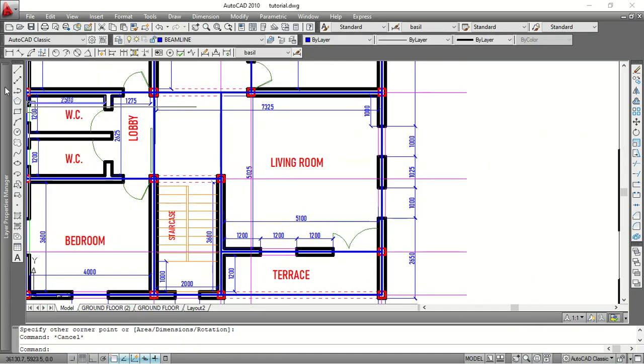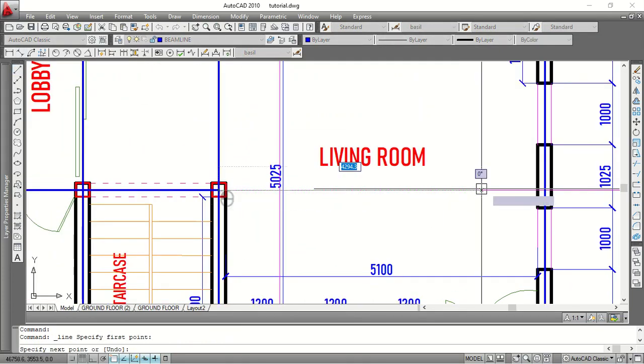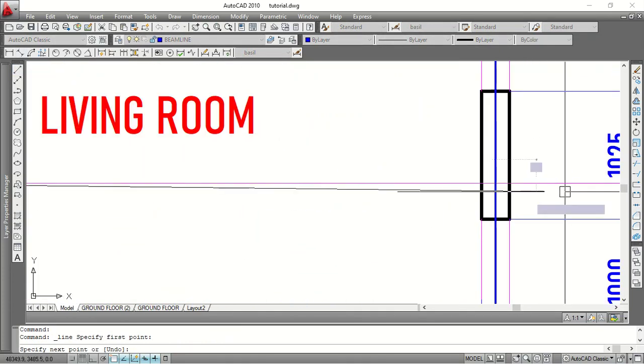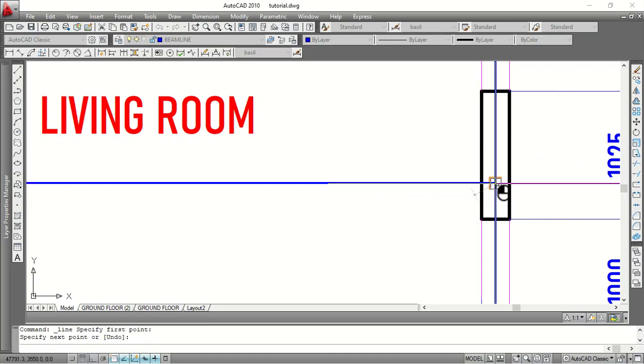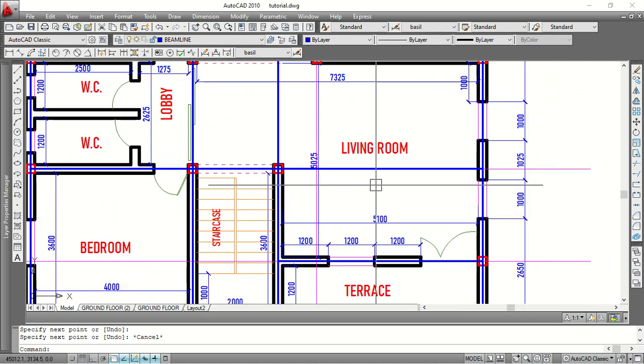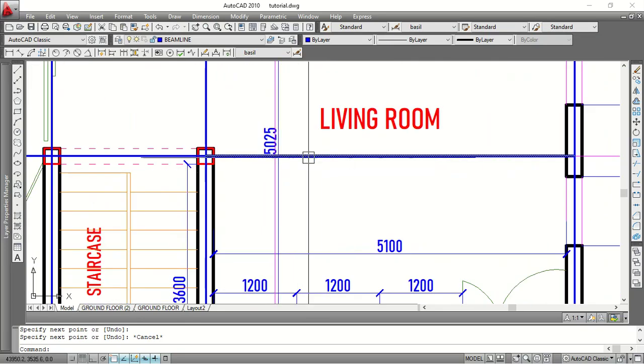What I often advise people is when you have situations like this, you don't just leave this open because this is a large floor area, a very large floor area. So it's often important that you create another beam here. Most times your client may say, I don't want to have a beam there, you know. But in situations like this where maybe your client is not ready to use a rib slab for this area, you can use what we call a concealed beam, but this will not be completely concealed.